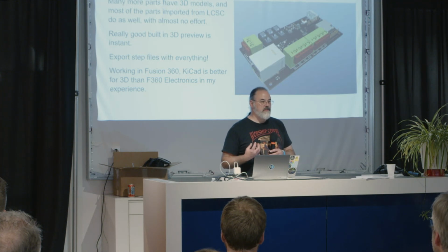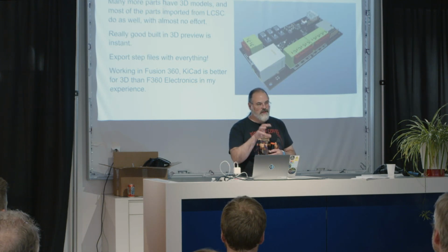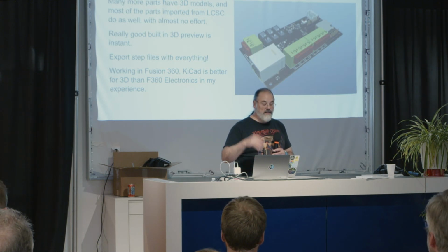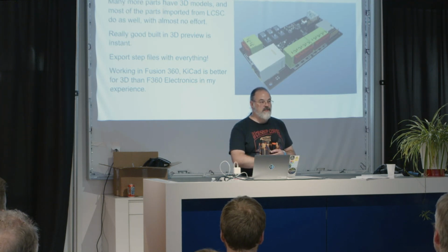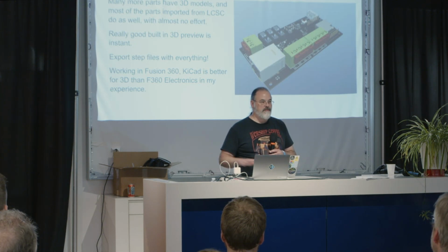I was able to pull in the 3D of this and make sure that I can actually have accessible fuses and things like this. Plopping in a special red-blue LED, checking that out, making sure all the stuff's in the right place. The 3D actually ended up being incredibly useful. The only thing that it was missing was this JST connector on the top right. 99% of this, I had to touch nothing to get 100% STEP export. Colors, everything. It blew me away.